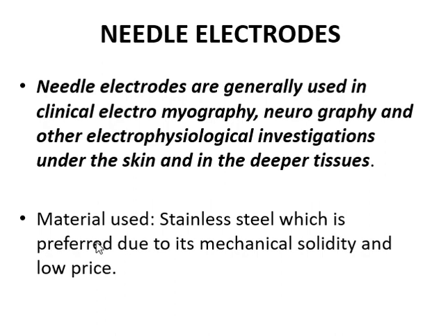The needle electrode is made of stainless steel. The monopolar needle electrode has a very finely sharpened point and it is covered with Teflon or other insulating material over its entire length except for a 0.5 millimeter exposure at the tip.